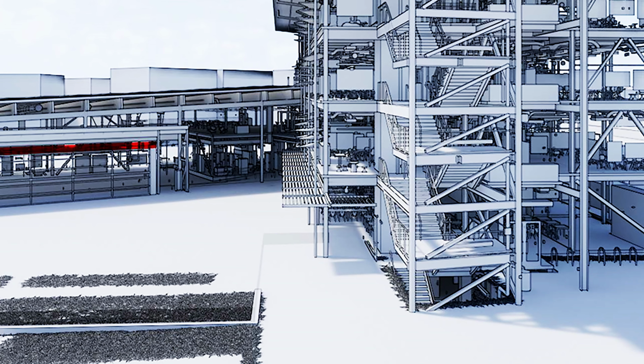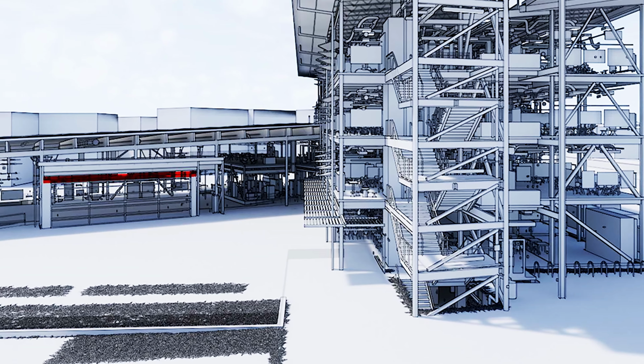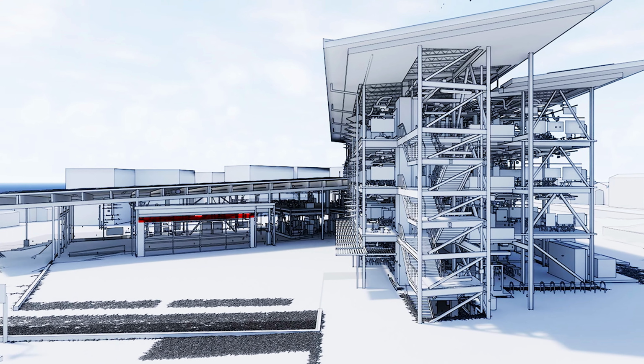So we've done this by working to build a better envelope, drastically reducing our air infiltration by 70 to 80% on the total CFM per square foot of leakage, but then also right-sizing the HVAC system and then over-ventilating. We're adding more air into the space, but we're bringing it through an energy recovery and increased filters, both active and passive. All these things are much better for today's design world in these post-pandemic design concepts. We're increasing the opportunity to actively grab the virus or passively filter the virus.